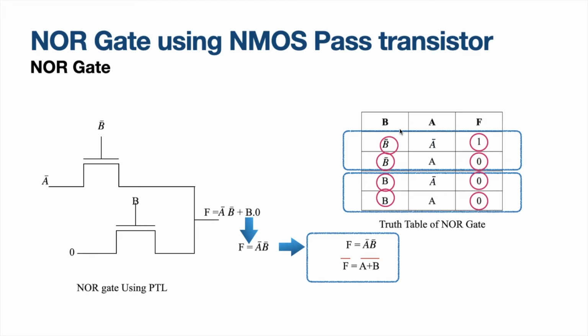With all these ideas, let us try to club inputs together as we did for the OR gate. So right now we are considering the first two rows where the B bar signal is common. Compared with the output, it is 1 and 0. There is some difference, so let us compare this F with A now. If it is A bar, the output is 1. If it is A, the output is 0.